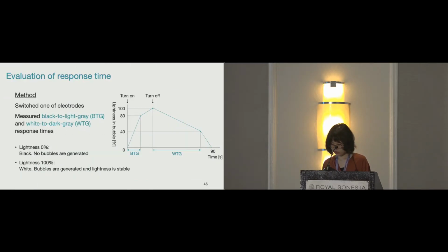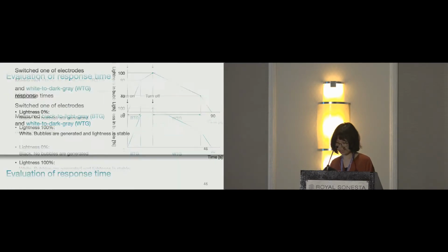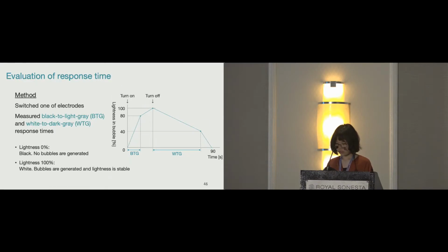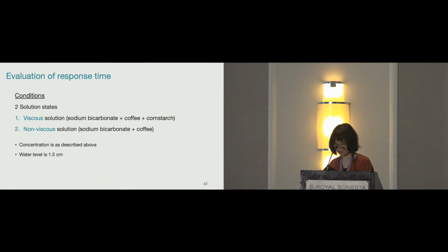Next, I'd like to quickly talk about technical evaluation. We evaluated the response time of our display. We switched one of the electrodes on and off and measured black to light gray and white to dark gray response times. The black to light gray response time was time lapse between black and 80% of the maximum lightness by generating bubbles, and the white to dark gray was time lapse between white and 40% black by the fading of the bubbles. These response times were measured for a viscous solution and a non-viscous solution, respectively.